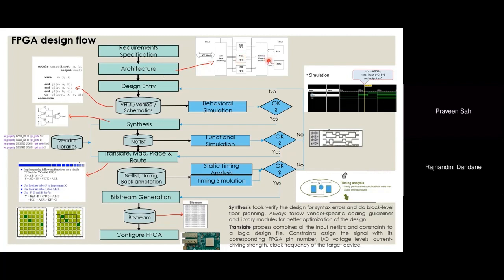For example, here you can see there is some external memory interface. It can be RAM or anything, and you want to interact or communicate with this memory using an FPGA device. So what are you doing in the FPGA? You are implementing all these logic blocks. You are implementing this FIFO, read, write FIFO, and these are the commands for reading and writing, and commands for controlling. And you are using some AXI interface. AXI is nothing but a kind of chip to chip interface. So you are using all these logic blocks inside your FPGA.